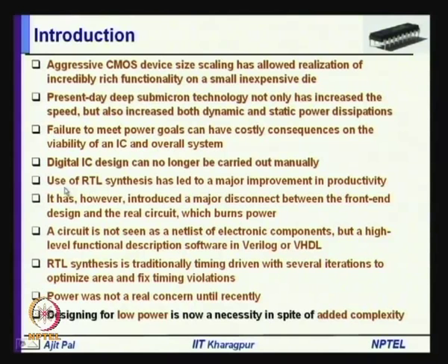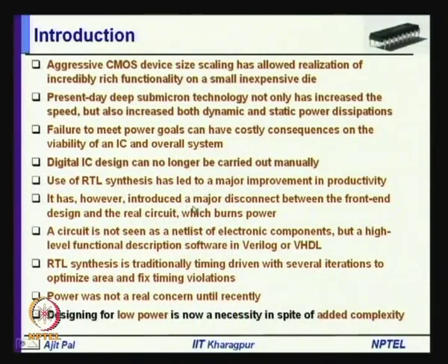The answer is no. Traditionally, use of RTL synthesis has led to major improvement in productivity. All of you may be familiar with RTL coding, writing programs in Verilog or VHDL. There you write your system level functionality with the help of Verilog or VHDL. However, this has introduced a major disconnect between the front end design and the real circuit which burns power.